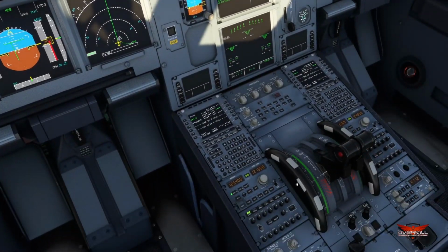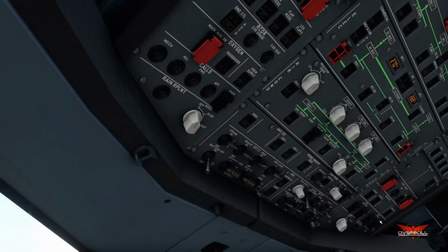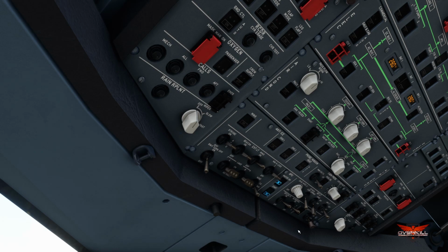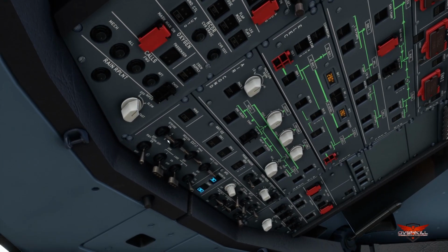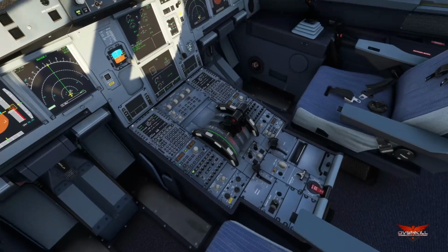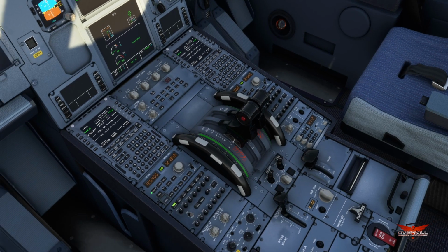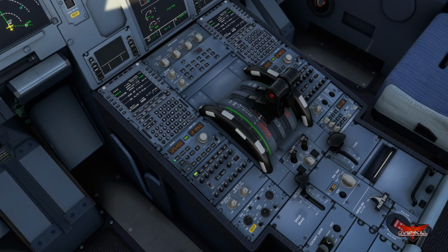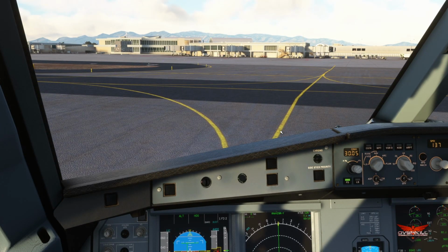Alright. Flaps up. APU on, in case needed. Landing lights off. Taxi light stays on. Transponder. Strobe light. TCAS. Predictive wind shear can remain on, but we're good. Go ahead and turn it off. We're heading to the gate here.